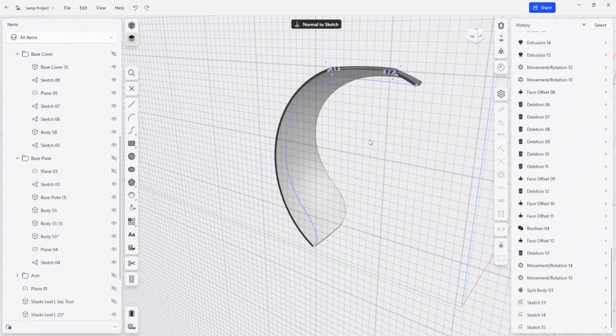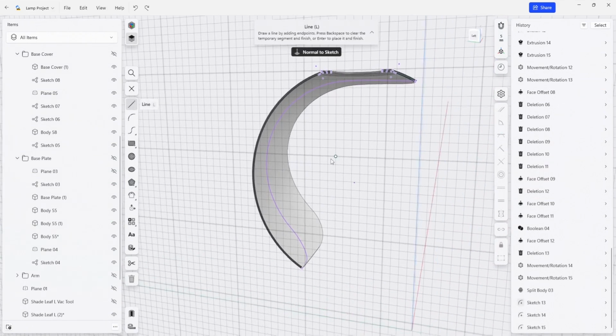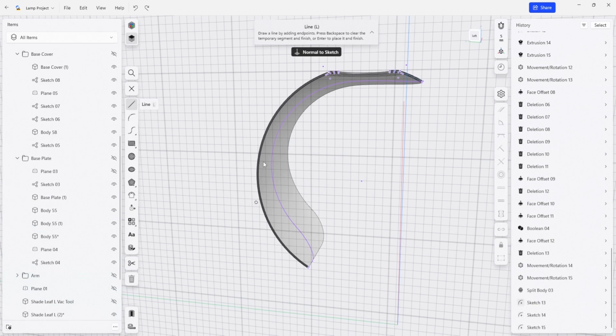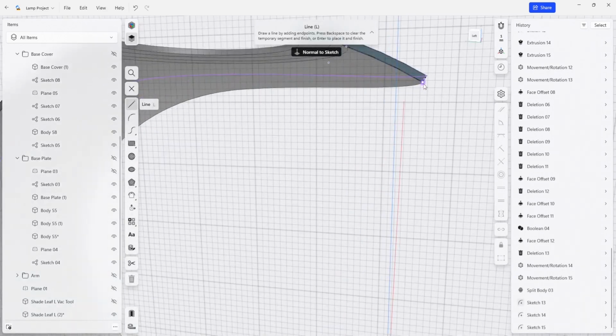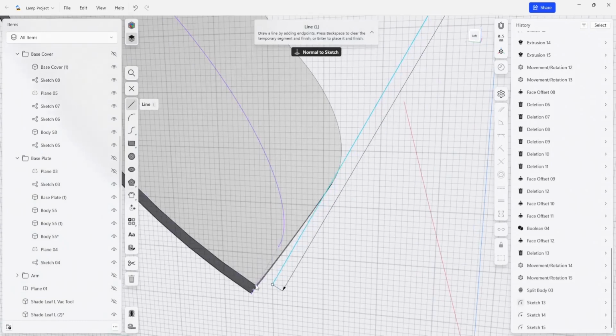projected to the surface, I am now going to start building the outer face of the tool that we're going to use. So we used an inner tool for a vacuum form, and we're going to use an outer tool to trim the component. One of the flat faces that we're going to use is over here to be able to trim away a lot of this inner surface here. We're going to do a left half, and then we'll mirror it and turn it into a right half. But we're just going to start off drawing some structure so that we can align everything.